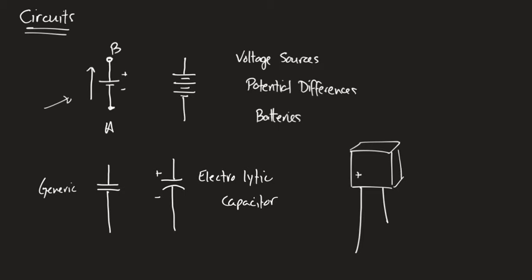Yes? Do they write the plus and minus on the side, or do we just assume it? Most of them have them on there. In fact, I don't think I have a bank of capacitors that doesn't have them. If it's an older round capacitor, because I have a few that are in the millifarad range that are round like this. They look like little cans, and they'll have two wires coming out. They'll have a stripe on one side, one of the wires. That stripe is the positive side. And usually it's got a lot of plus signs on it, so it's pretty easy to tell. But they get handled by people, and some of that stuff wipes away. So the wire length, the lead length, is the other way that you can tell.